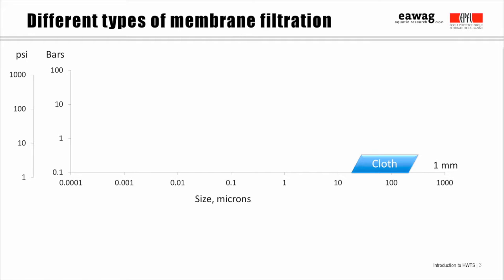The guinea worm larvae, which is transmitted by copepods, little water insects around 1 millimeter in size, can be effectively removed with cloth filtration. Studies in Bangladesh have also shown that cloth folded over 4 to 8 times has an effective pore size of about 20 microns, and cholera is also transmitted at least partially through copepods, so studies have shown that the use of cloth filtration can reduce cholera by about half in Bangladesh.